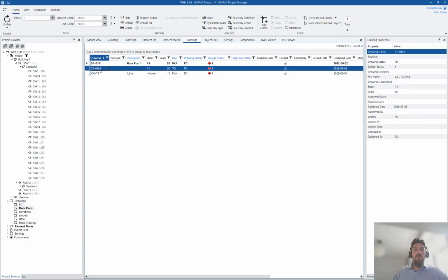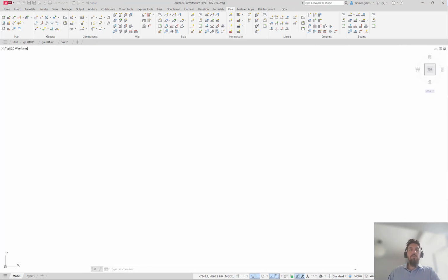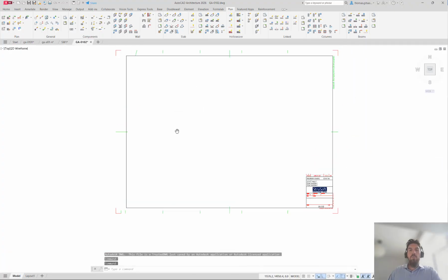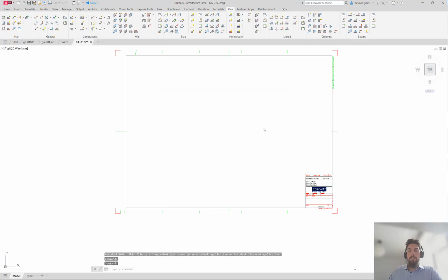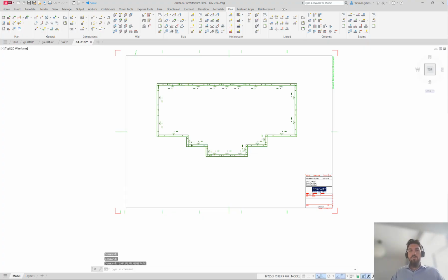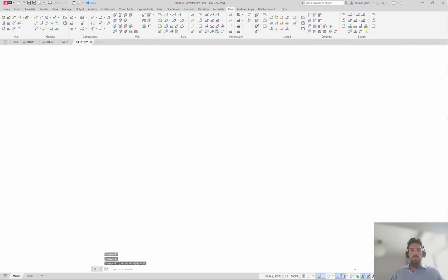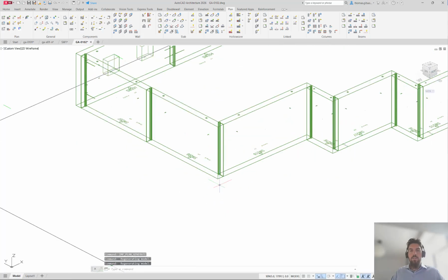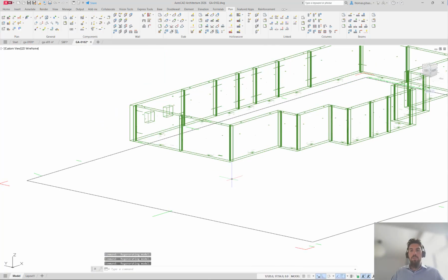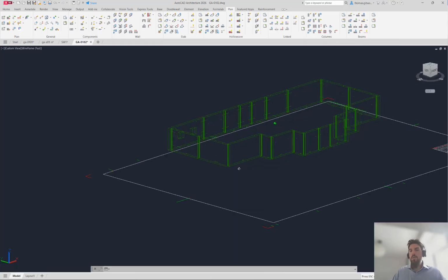and then say that this is going to be my second floor, say OK. In my second floor, I can just open my drawing for the second floor, generate my walls. I don't even need the floor layout anymore. Floor, building 1, floor 2, say OK. Generate the walls with the custom materials in full 3D, same as before. And you will see now they are also on a different elevation, right? The elevation here is not at 0 or 15 millimeters above the ground floor, it is 2,615 or something, one floor above.